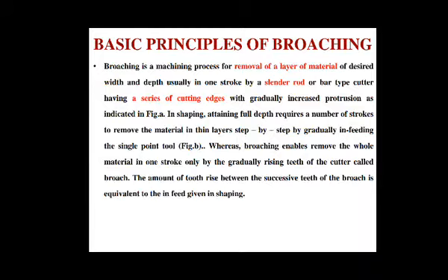These are the basic principles of broaching. It is a machining process for removal of a layer of material of desired width and depth, usually in one stroke, by a slender rod or bar type cutter having a series of cutting edges with gradually increased protrusion, as you can see in the figure.